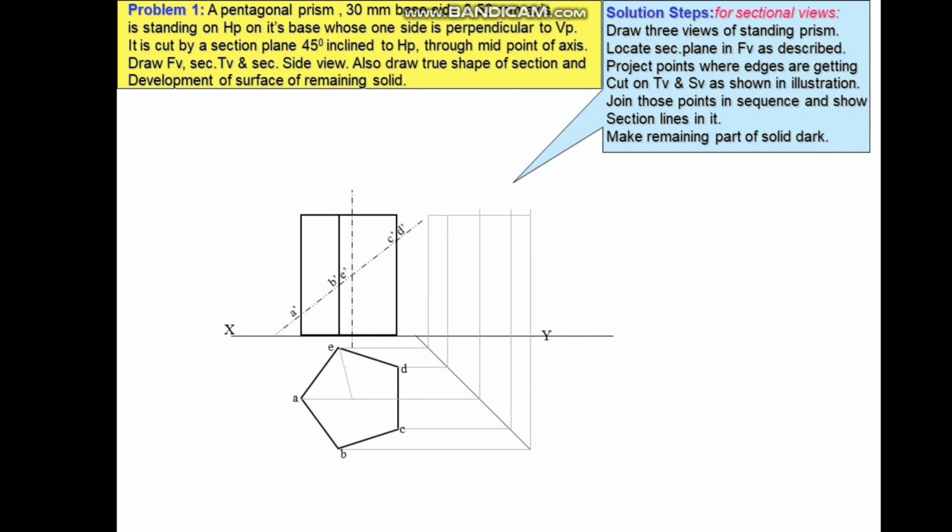Now that is done. So this is to draw the side view. Side view won't be asked mostly. If at all it is asked, you have to draw a 45-degree line, project all these points to this line, project it upwards, and from here project it again. So when you project it like this, the sectioned points, you can see the point where D and D dash marks, you have to mark it. The point where B and B dash marks, you have to mark the point. Mark all the points, join it, and join the remaining cut section.